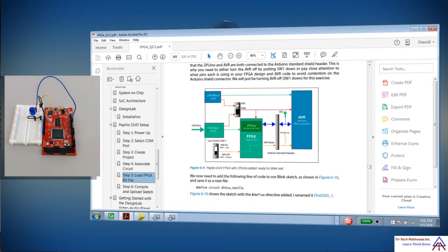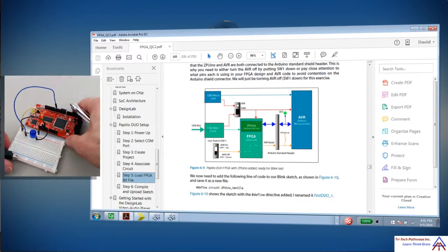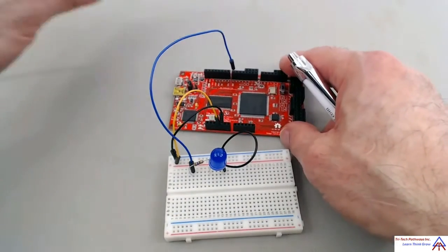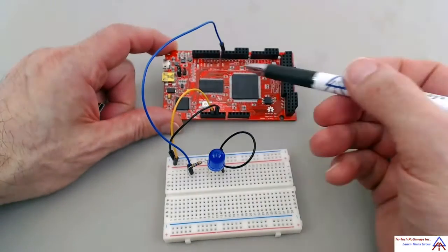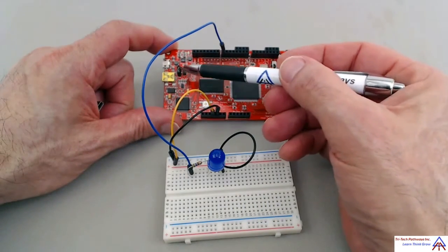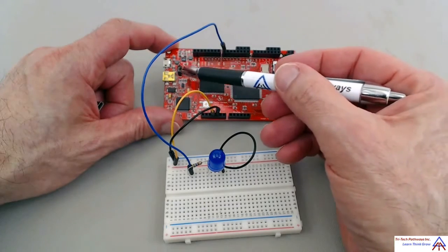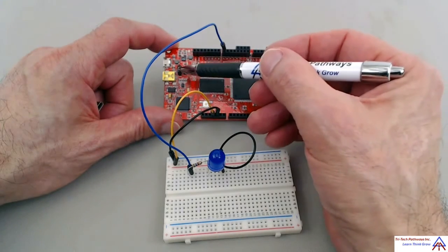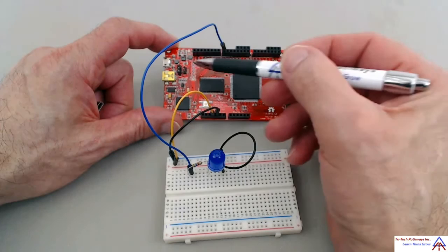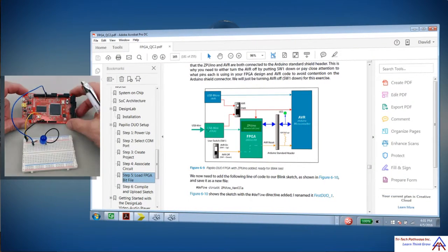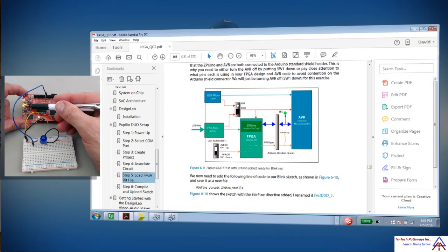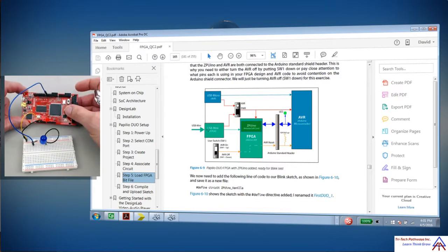All right, so from that drawing, we can take a look at that. Here's the USB cable. Here's the jumper strap, and when we're just programming the FPGA, you're going to make sure the jumper strap is in the bottom position when the board is held this way, and the mini USB connector we'll be using to program the FPGA.